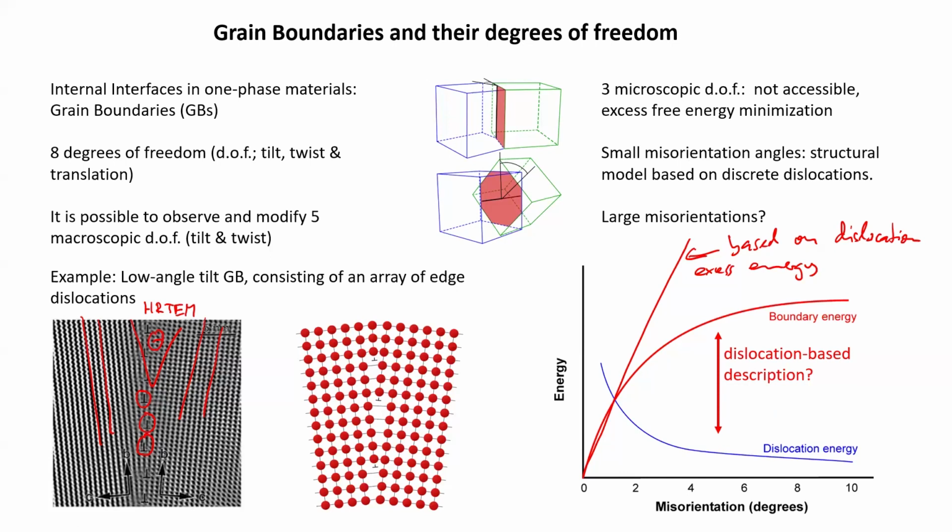So for the typical grain boundaries which we see in a polycrystalline material, which we can identify by microscopy, it's mostly the high angle grain boundaries, and they are actually not covered by this dislocation-based description because dislocations would come too close. Additionally, if you have a real material, not a computer simulated one, you always have impurities, because of mixing entropy reasons. There cannot be a pure material.